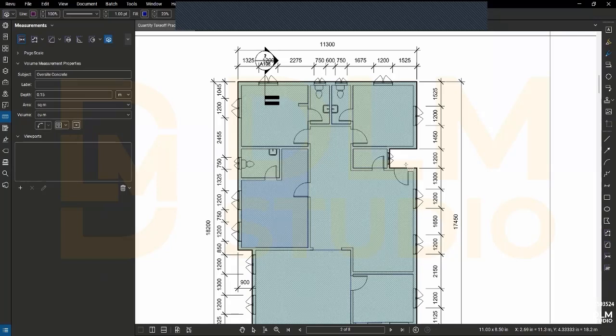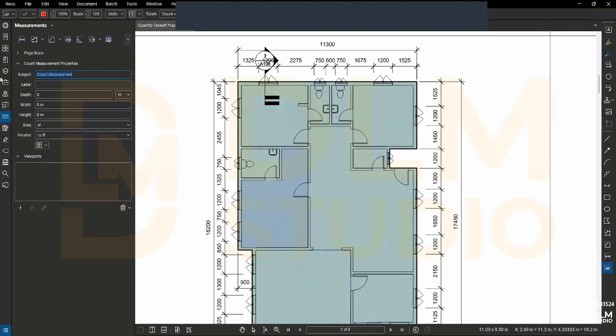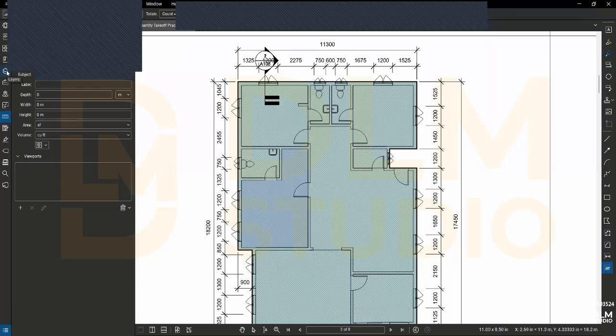Now, you know how to use all of these tools. You have your Excel templates on one side, you have your tools or software on the other side. Just come here and click the measurement, and you have those quantities. Don't worry, you will see the summary page very soon. Let's move to the next part, which is the count. For count measurements, let's say windows, and the label should be, let's say, 1.2 meter by 1.8 meter.